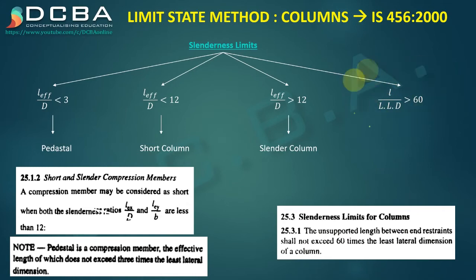So if a column has a slenderness like this, it is not allowed. You have to revise the depth or the length of the column, either of them.